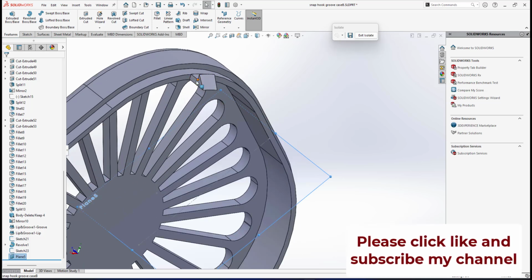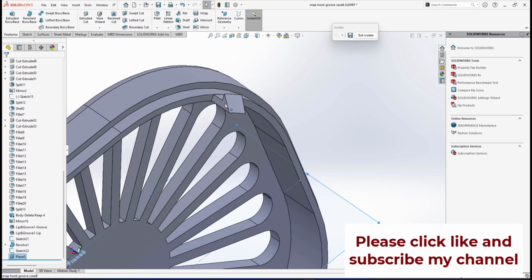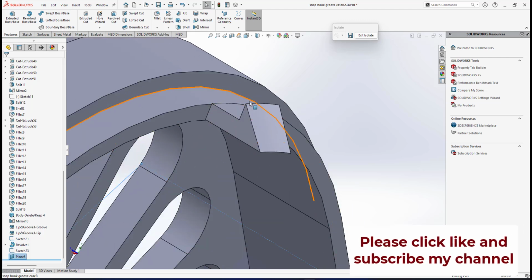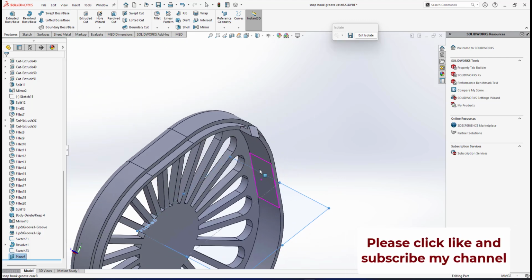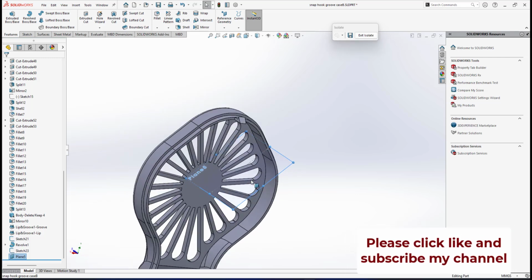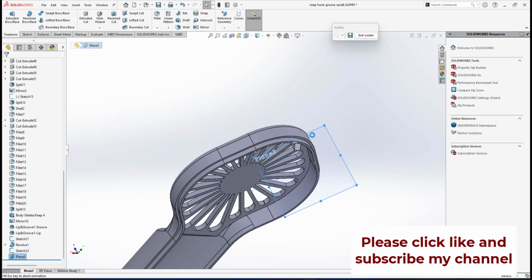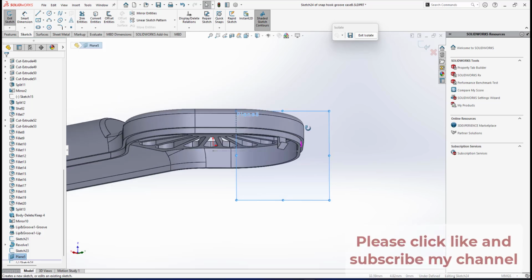But the profile that I will create has a slightly different dimension, which I will show you. That's the reason why I don't want to make the height the same. If you look at this, my profile from here is 2 millimeter. The vertical height from this point to this point is 2, so I will make it less than 2 to avoid zero thickness. Okay, later I will show you why. Alright, this is the plane, and I drag the plane like this. So I will create a sketch on that plane.